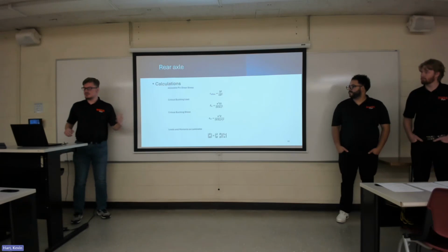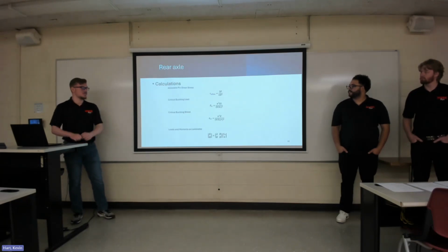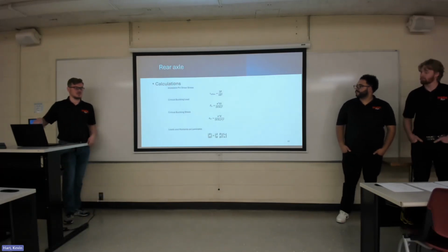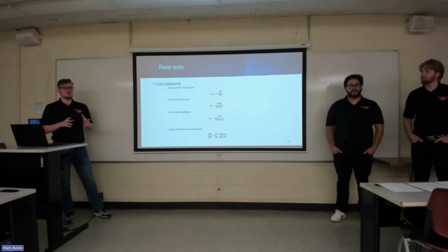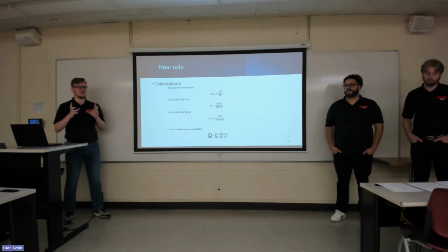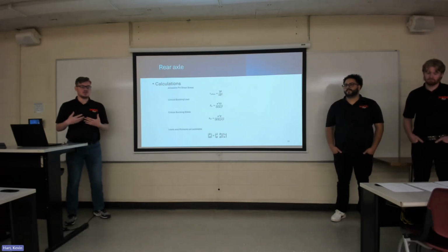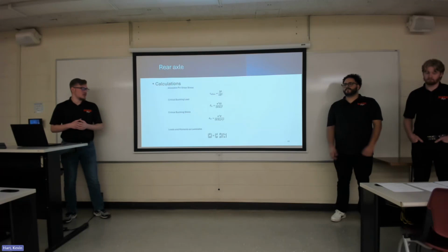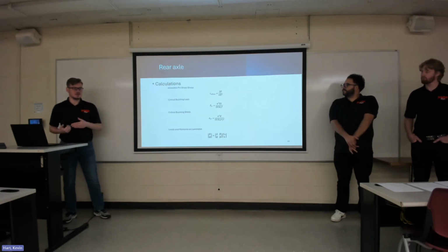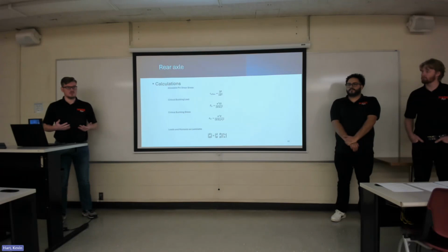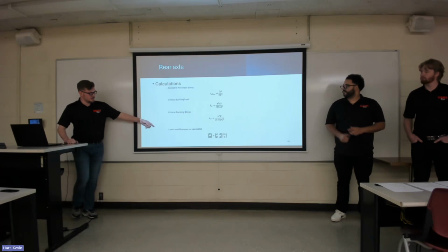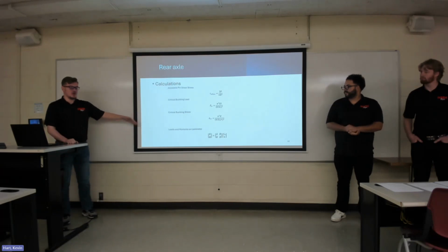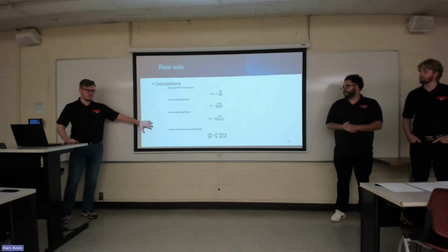The following calculations are a collective sum of equations I had determined would be necessary for the analysis of the U-joints and axle. The allowable pin shear stress is meant to do analysis for those pins that will be experiencing a lot of the shear and force within the U-joints themselves. The critical buckling for the load and stress of the axles is also important because they will also be carrying weight. Another one is this bottom equation here of the loads and moments on laminates. I just didn't have a real good name for them like the others.